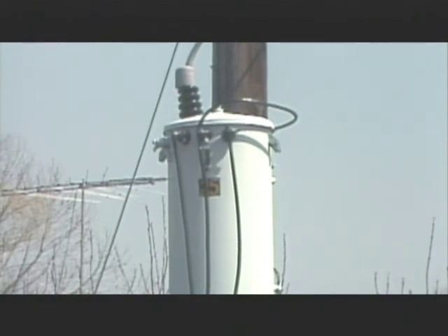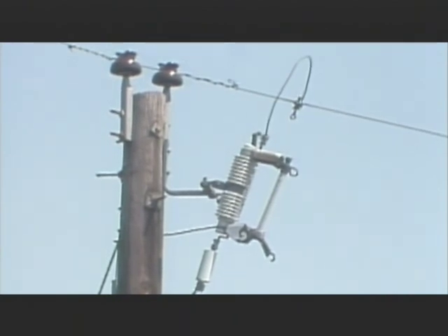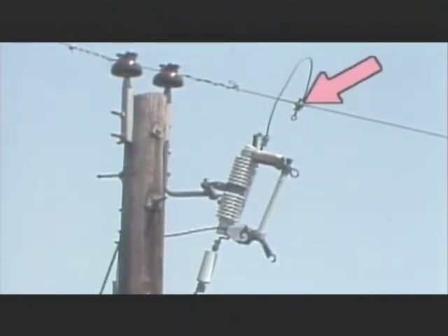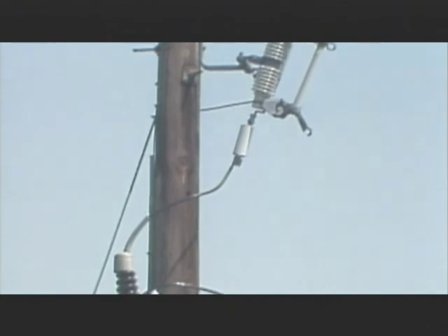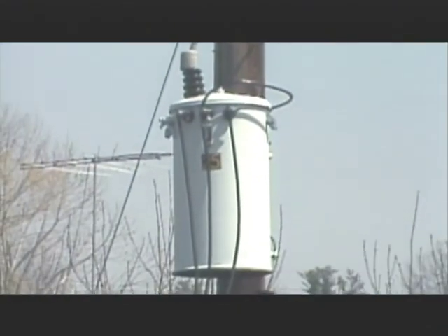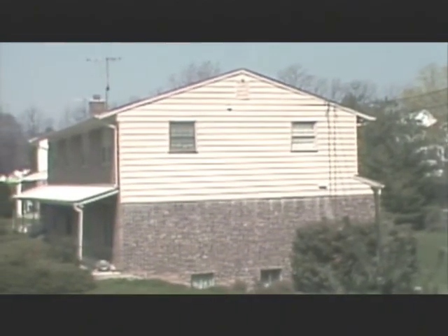to a feeder. The transformer receives electricity at a primary distribution voltage through a wire tapped off of a feeder. The transformer steps down the primary voltage to a secondary or utilization voltage, which a customer can use. Wires passing through the bushings on the secondary side of the distribution transformer form a secondary bus, which supplies secondary voltage to a consumer by way of a service drop.